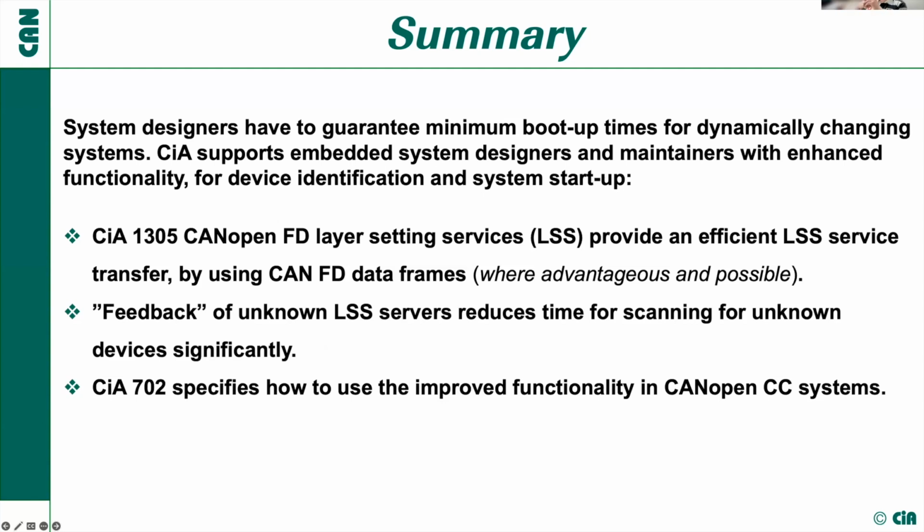So we cannot send simultaneously from different devices the same CAN frame in CAN-FD. The feedback allows us to identify unknown LSS servers in a very reduced time. And we have furthermore the document 702. If you're still staying with CANopen Classic systems, then you see how you can use this added functionality also in these kind of environments.